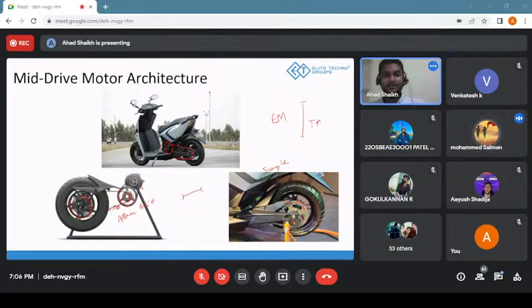Yes, great. So I would also like to add to Salman's point that belt drive belts are cheaper to manufacture as compared to chain drive, and they're also lighter in weight. Lighter the weight, we can reduce the overall weight of the vehicle. And in a belt driven mechanism, we don't need any kind of lubrication, because there are no metallic components.